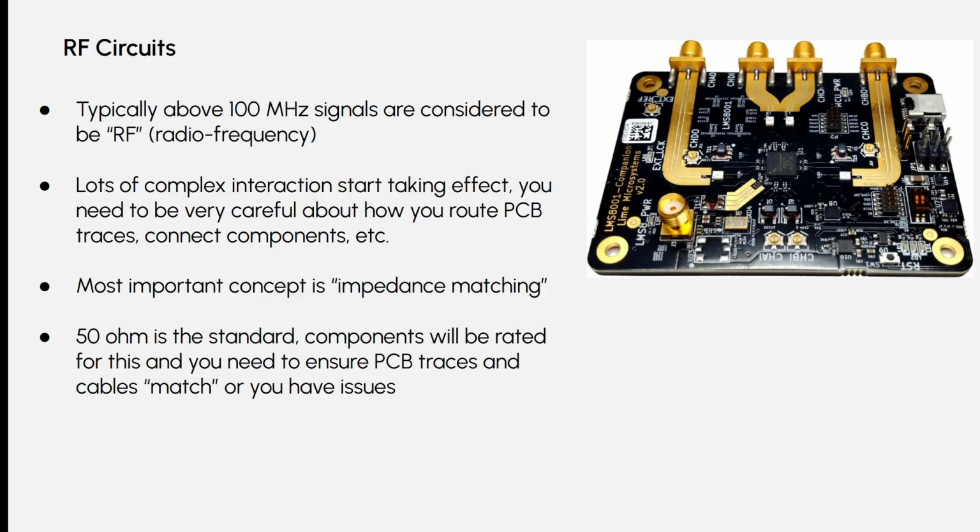You cannot discern from what it originally was because you get so much interference between the different frequencies, because you basically get reflections whenever there's a mismatch. So basically you want to make everything be 50 ohms. Part of this is mostly solved by buying components that say 50 ohms on them. And part of it is also solved by when you make a PCB, the traces need to be a very, very specific thickness depending on the distance to the layer below. And it's just something to be aware of if you're doing the RF stuff.